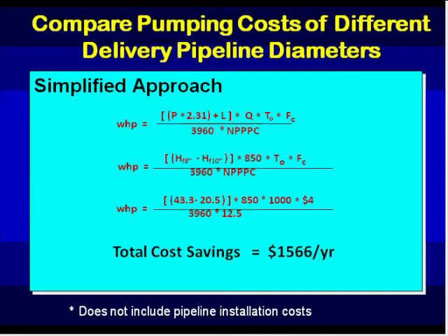The equation that we're going to use here now is to calculate the water horsepower, because that's what we really do use when we're figuring out what the energy cost is going to be. And so as we look at this then, the water horsepower hour calculation is based upon the pressure or total dynamic head that's here, the pressure plus the lift.